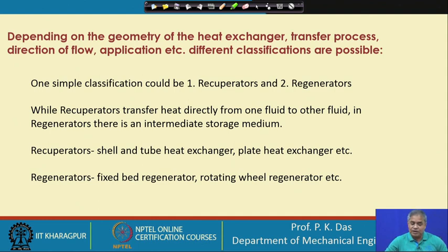Recuperators transfer heat directly from one fluid to another fluid. Of course, these two fluids may or may not mix with each other. There could be a separating wall, a solid wall between these two fluids, but there will be direct transfer of thermal energy from one fluid to another, and this is called a recuperator. Most of the heat exchangers we see around us and most of those used in industry are of this class. Examples are shell and tube heat exchangers, plate heat exchangers, fin tube heat exchangers and many others.